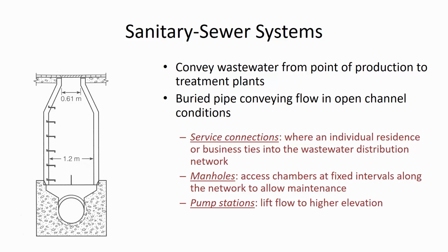And they do that intentionally so that when tree roots or whatever else may cause problems with your lateral connections, whenever there's an issue, then that's your responsibility to have someone come out and fix it. Because those are the most vulnerable pipes, the ones that have the smallest diameters, that are at the shallowest slopes, and that are closest to vegetation, because they can become clogged and broken pretty easily.